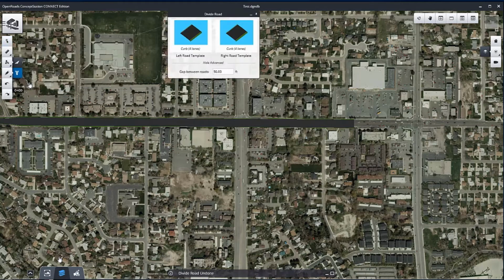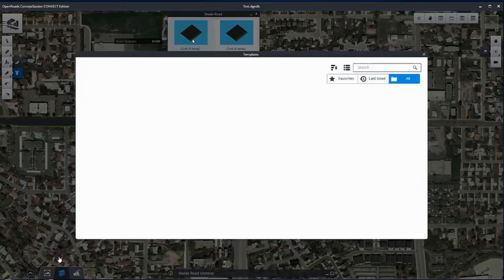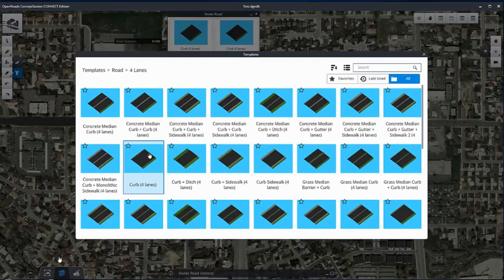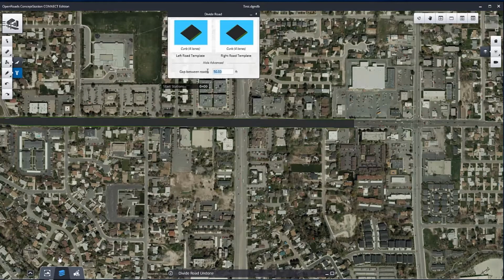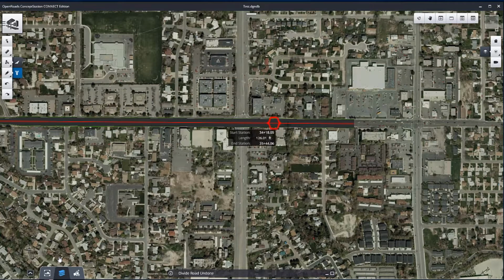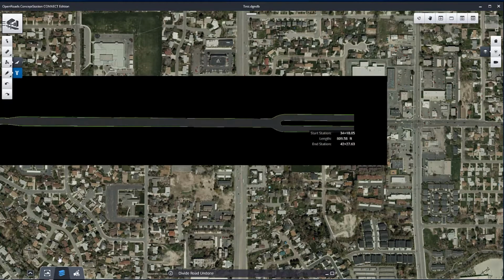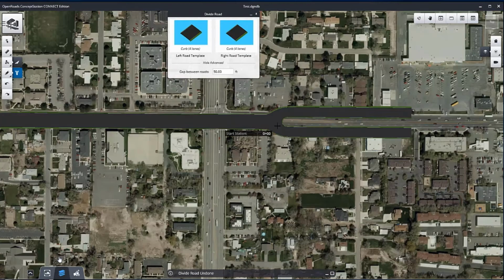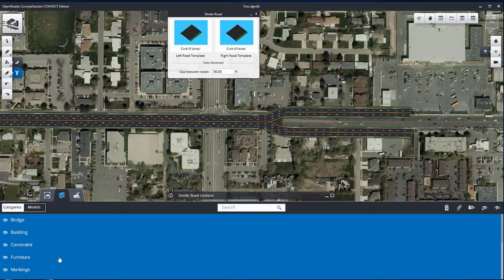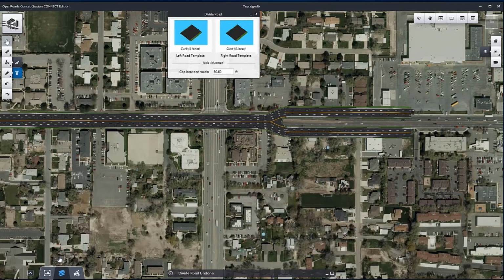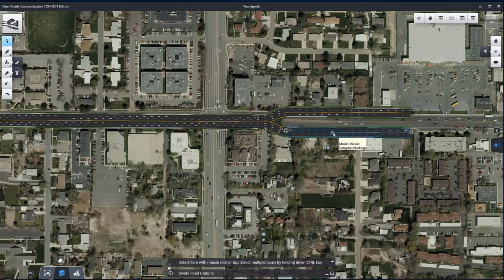And one of the things you'll want to consider when you're doing your design is you've set up a geospatial projection when you began, and that projection would be either in metric or survey feet or international feet, depending upon where you're designing in. Well, you'll also want to make sure that your readouts on the settings match that, so that when you actually go out to export your data, everything is synced.